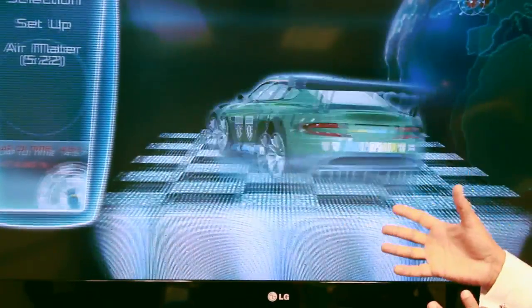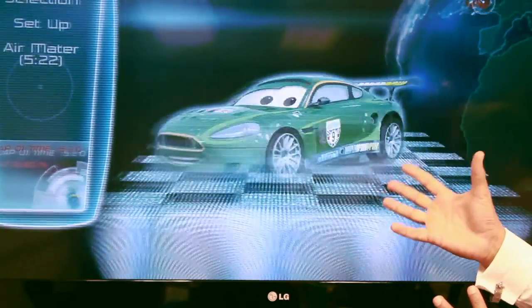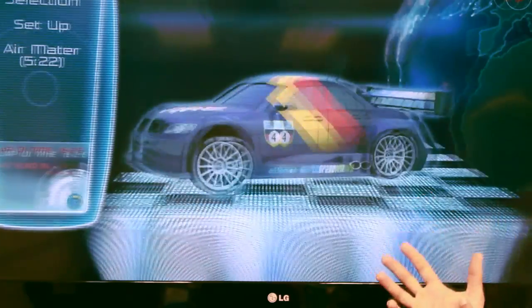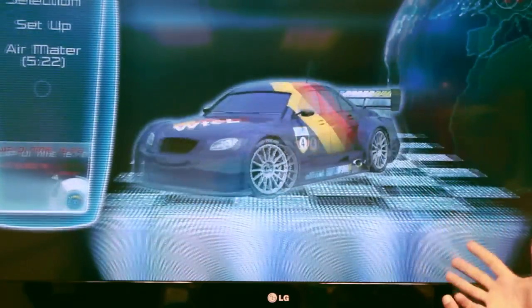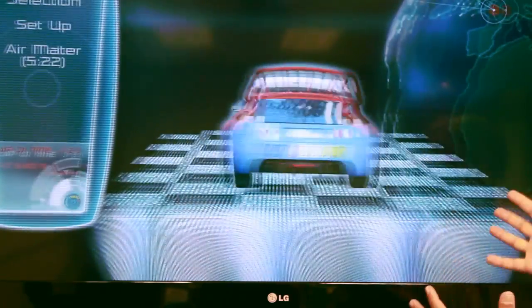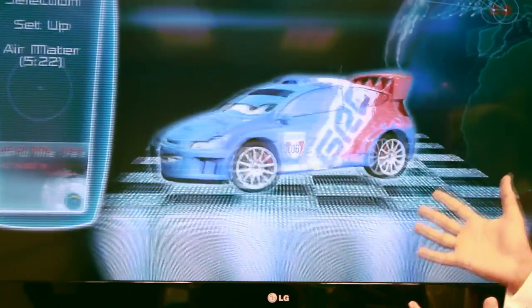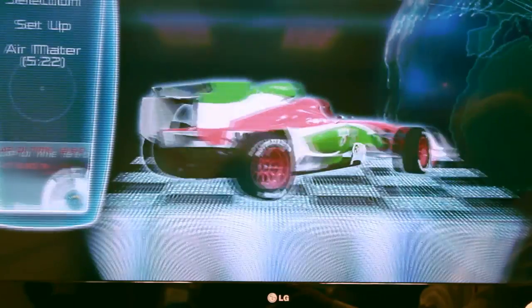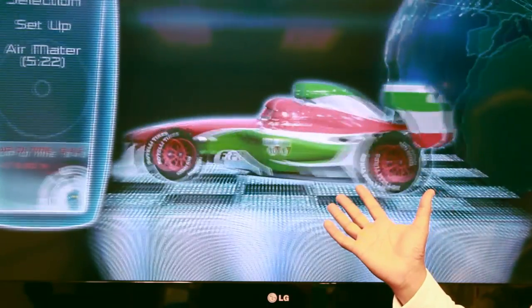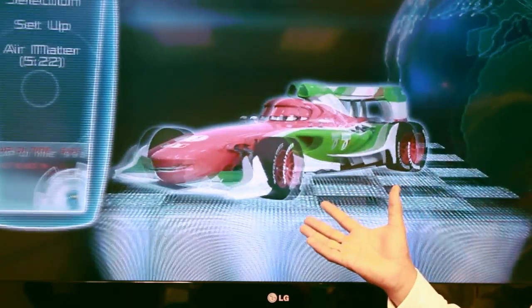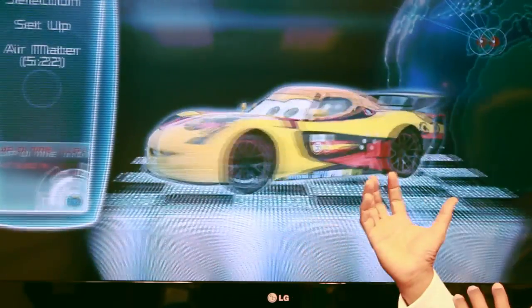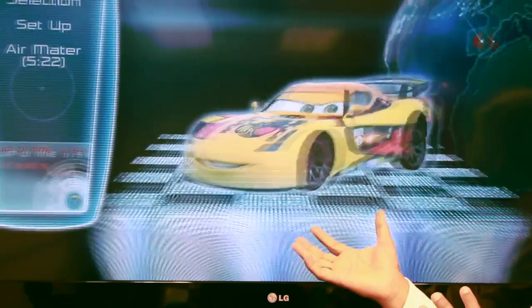It's not clear, it's not crisp. It's sort of ghosting, double image, 2D images colliding, however you want to express that. But this is a 3D image, and I am getting a 3D image. And I was able to achieve that by going to 60 hertz. At 120 hertz, with dip switch number 1 being in the up position, I was unable to get this television to operate. So this is my setup.